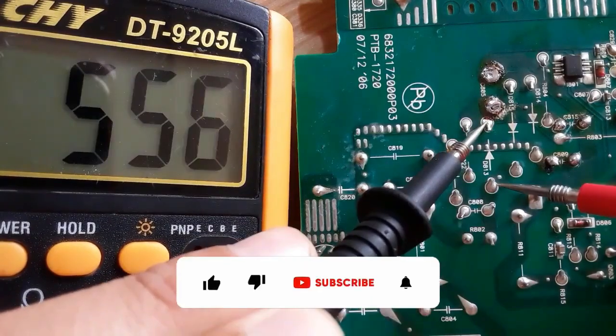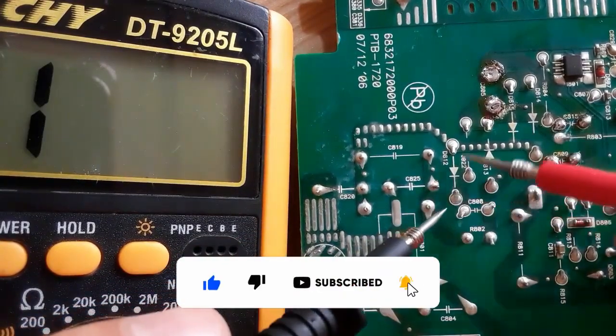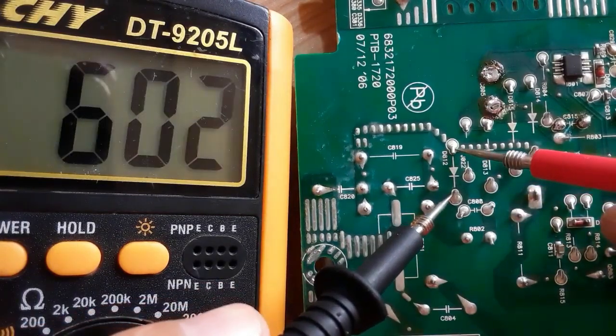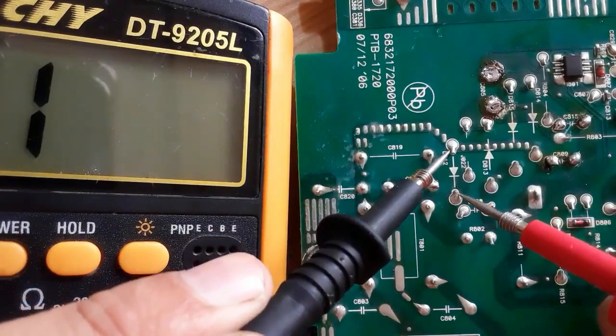We get a reading. If we swap the probes, no reading. This is a good diode. The last one, we get a reading. If we swap the probes, no reading. Means this is a good diode also.